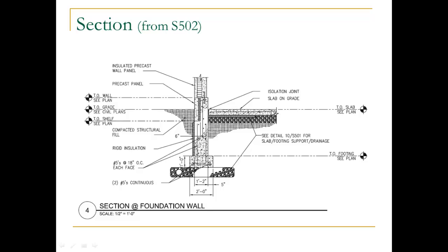There's our concrete slab on grade with reinforcing, and we have an isolation joint right along the edge that allows us to allow some movement without cracking the concrete, because as we know as civil engineers, concrete is brittle and it will expand and contract, and if it doesn't have anything to move against, it will crack in some very ugly conditions.